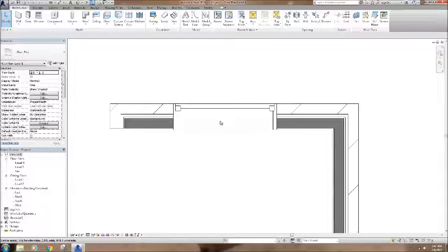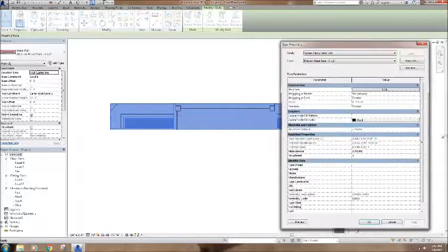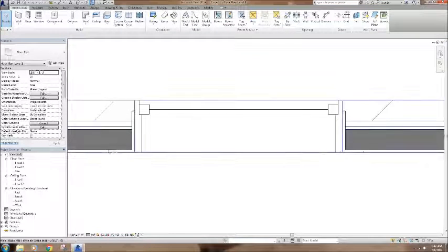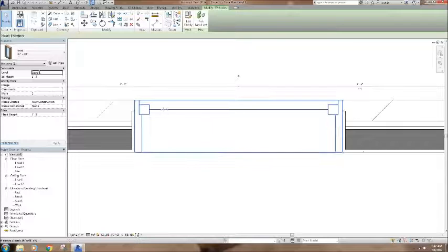Okay, so there's this window in here. I've got all my layers just terminating there. If I go into wrapping at inserts, I can say I want exterior, interior, or both. I'm going to do both and hit OK. And so you can see this returns the chipboard inside. Now the reason it's coming into the brick is because of where my window is set.